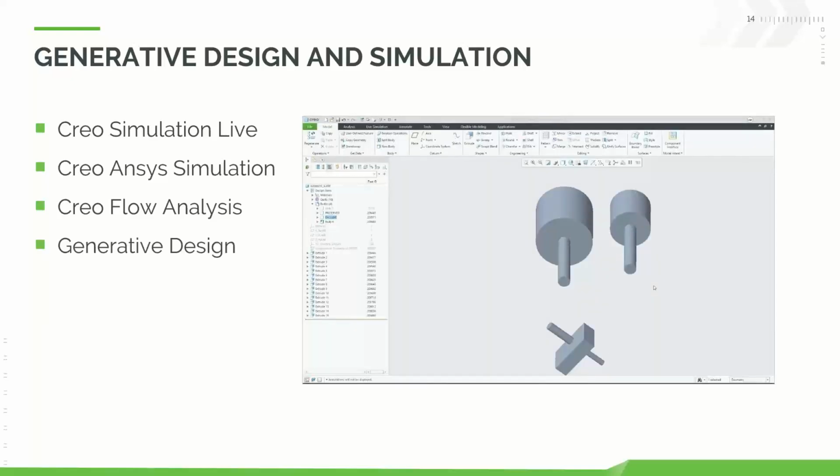Generative design got some improvements. We now have the concept of a safety factor to minimize mass at specific safety factors. Another thing we can do is modal analysis here as well. It means maximizing a fundamental frequency for a mass volume target, minimizing mass for some frequency floor. So those are definitely some welcome improvements. We added in support for ball joint constraints.